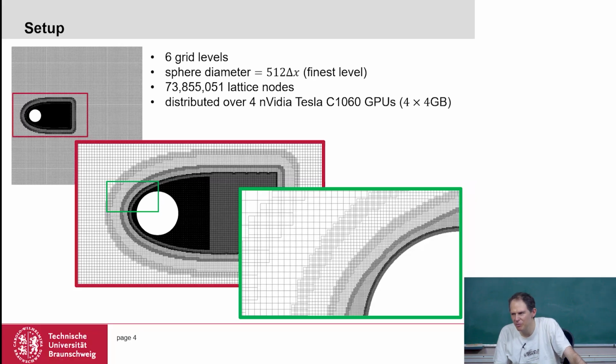So Cartesian grid method means we cannot easily use a very fine grid at the boundary layer. Yeah, so we can of course refine the grid. But other than, like in OpenFOAM, where you have these boundary elements where you have very high resolution directly on the boundary, this is difficult to do with a Cartesian grid method, because changing the resolution is not straightforward.